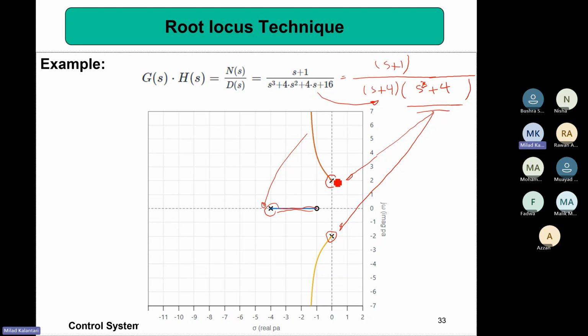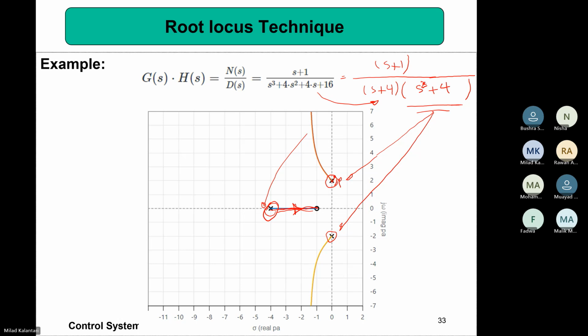We should figure out how the poles are exiting from these locations. For this one it is clear because it goes just to the 0. For the other, again, you need to draw some unknown field of the exit from this pole and then try to calculate the phase of that imaginary point respective to the other things, right? So let's say from this pole, the nearby pole, the phase is negative phi.